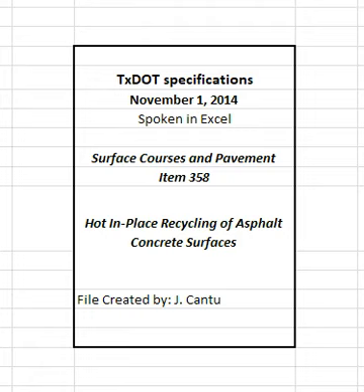Dry the core holes and tack the sides and bottom immediately after obtaining the cores. Fill the hole with the same type of mixture and properly compact the mixture. Repair core holes with other methods when approved. 6.3 Placement Testing. The engineer may measure in-place air voids at any time during the project to verify specification compliance.